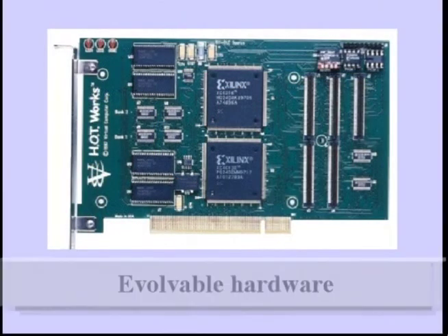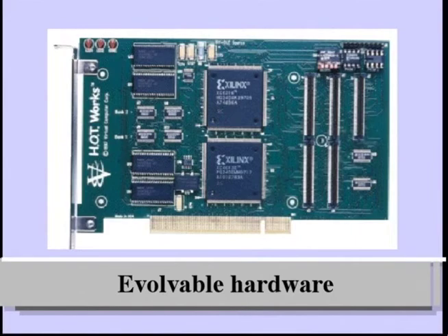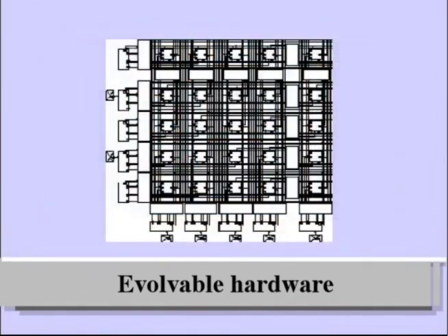Genetic programming can be efficiently parallelized, and parallel computers were used to produce all the results in this videotape. Some runs of the sorting network problem were run on evolvable hardware in the form of a $950 PC expansion board containing a 4,000-cell Xilinx 6216 field programmable gate array.